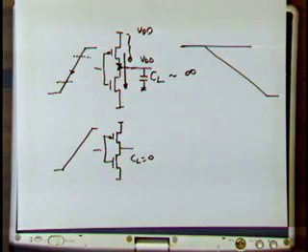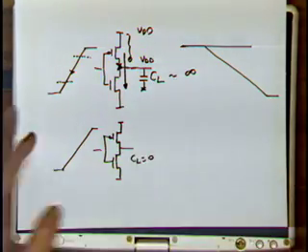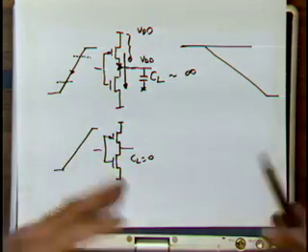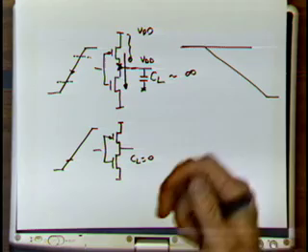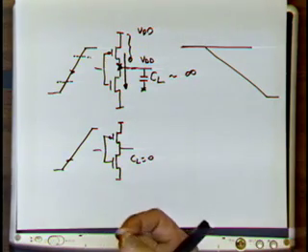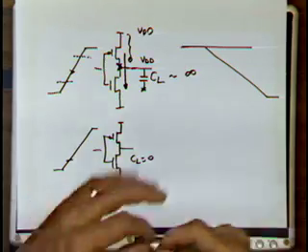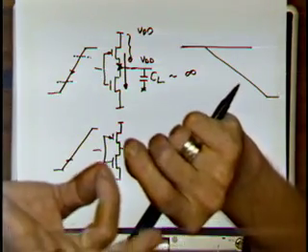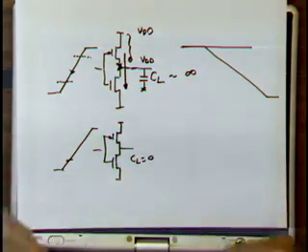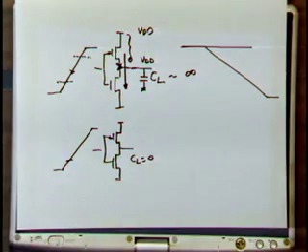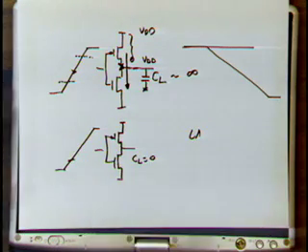It's going to be maximized. Because what's happening is a single leg, suppose you have no load capacity whatsoever. There's always intrinsic capacity, but assume you have 0. You turn this NMOS on, a single electron comes by, switches your gate from one to the other one, and it maximizes the voltage over your transistor. Bingo. PMOS will basically be sitting there dumping current, doing nothing else. So large, really fast. This gate is going to be extremely fast.